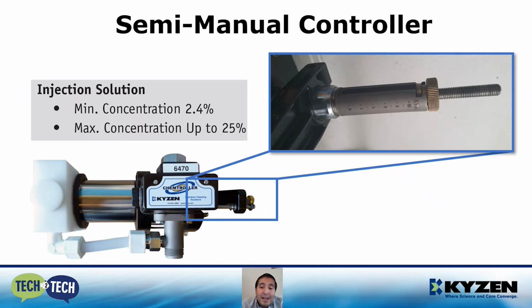The dial has a scale that goes from 0 to 10, where 0 means 0% movement of the piston and 10 means 100% of movement of the piston. It is important to notice that this scale does not directly relate to the concentration percentage of the mixture it will be supplying into the process.